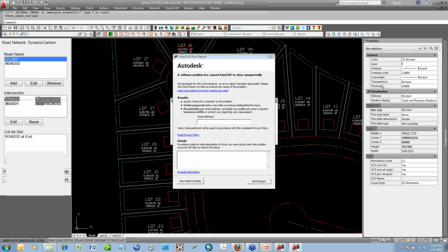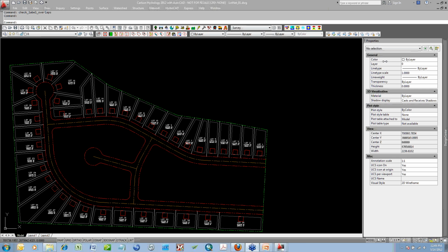So that's no problem. The other nice thing about the intersection editor is, like the profile editor that was shown at the very beginning of the presentation, there will be graphic tooltips out in the drawing file. So as you go ahead and pick those different tabs for front, rear, left, and right, you will also have the graphics in the main CAD window showing you exactly what it is you're working on. So if you're unsure how all that relates to station order, but lowest to highest is typical, you can always take a look at the CAD window to see what the graphics are doing.